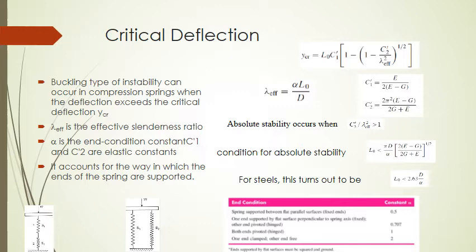If we cannot control the geometric parameters, like when we have some fixed length and some diameter that cannot be changed due to some spacing constraint, we can still maintain the stability by changing the material parameters like elastic modulus and modulus of rigidity.